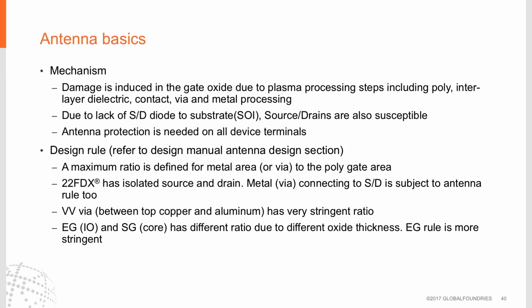The EG devices, which are the I/O devices, and the SG devices, which are usually the core devices, have different ratios due to the different oxide thicknesses. The EG rule is more stringent.